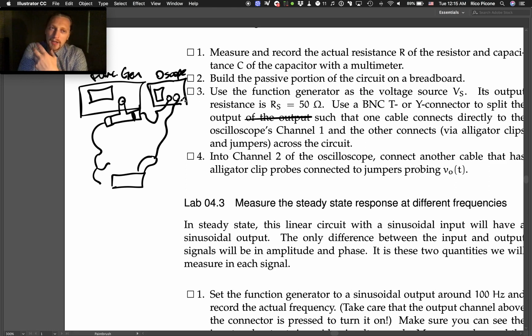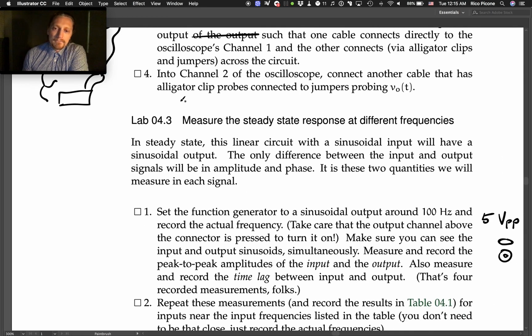Yeah, so set your oscilloscope up, and when you set it to 100 hertz input, you should set your time base so that you can see a 100 hertz wave reasonably well on the oscilloscope. So adjust it and get it dialed in, and then